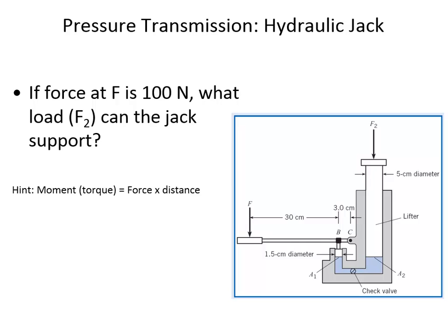So, worst case scenario is it's going to have something close to the unit weight of water. So it's going to be 1 meter times maybe 9,800 newtons per meter cubed. And so the delta P is going to be in the order of 9,800 newtons per meter squared. And so 9.8 kilonewtons out of 6.2 meganewtons.